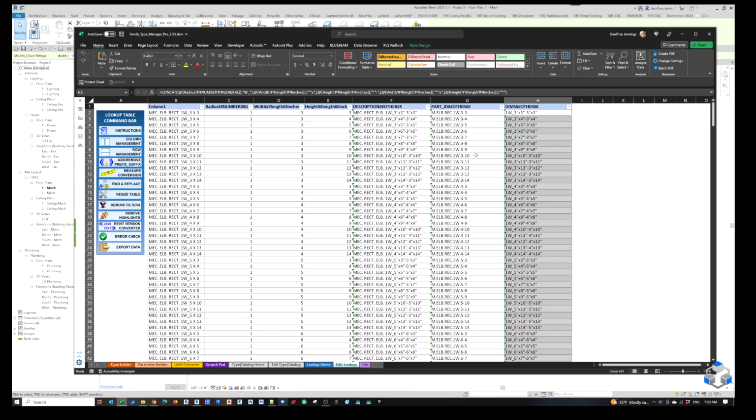So we now have created a lookup table that references all 432 unique possible conditions we have, and everything will be properly reported in a common shared parameter for all of your mechanical conditions. The same applies for mechanical or plumbing. So we have unified column collections across the entire model with these shared parameters.